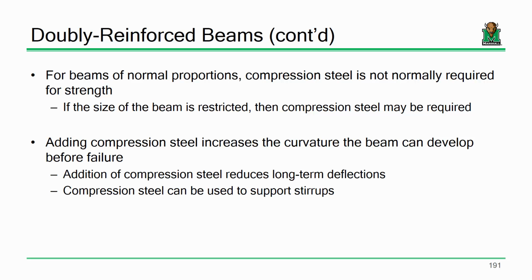Okay. All right, you see where I'm going with this. So you play a guitar, after so often, you have to take those guitar strings and you have to tune them. Now, what does it mean, really, to tune strings? You're tightening them. You are increasing the force inside those strings. But the strings didn't get longer and shorter. The length of those strings is maintained constant between the mechanism at the end and the fretboard at the other end. So the length is constant, but the force inside them dissipates. That's why the note gets weaker, and you have to tighten it. That's called relaxation. The force dissipates under a constant length. It's almost the exact opposite of creep, but it happens.